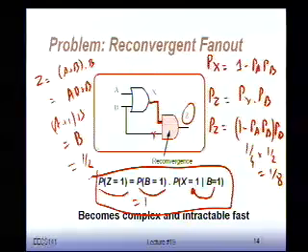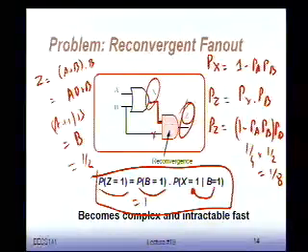The only thing I really care about is how often this node changes, given my logic topology. So from pure logic, high-level VHDL simulation, I can figure out all those switching probabilities. I extract my capacitances, I combine the two together, and I get my result. So that's the way power analysis is typically done.